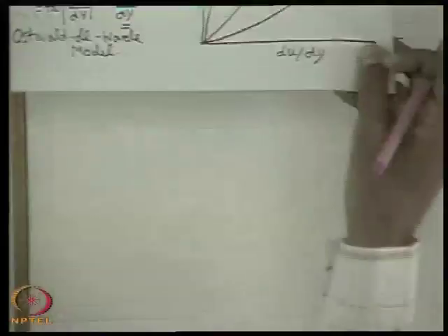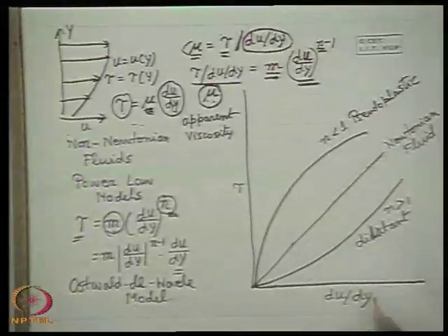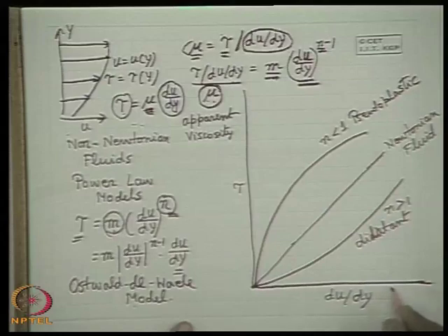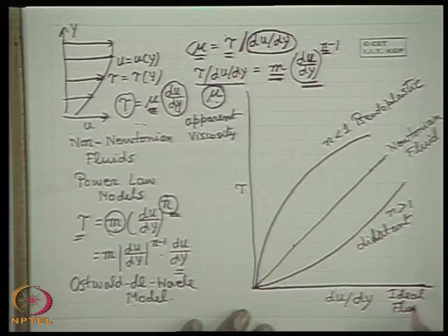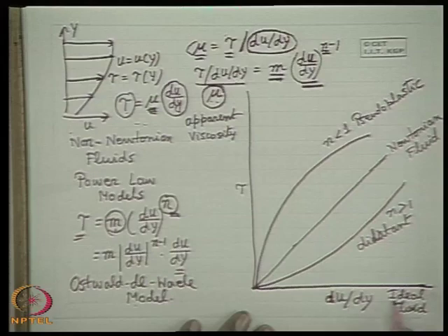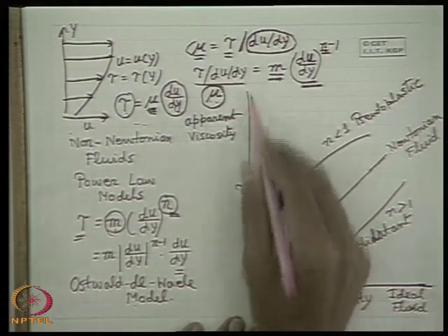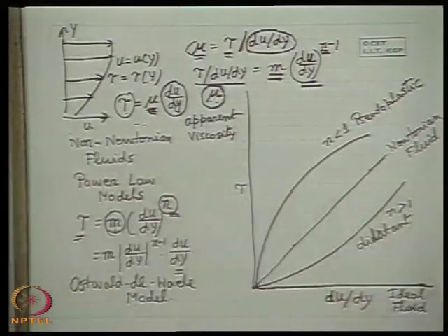So therefore if we see this curve, the abscissa represents ideal fluid. Why? If the viscosity is 0, for this ideal fluid, whatever may be its flow condition or whatever may be its velocity gradient or rate of shear strain, there will be no shear stress developed in the flow field. That means an ideal flow of fluid, or flow of ideal fluid, is devoid of any shear stress in the flow field. The shear stress will not be generated.